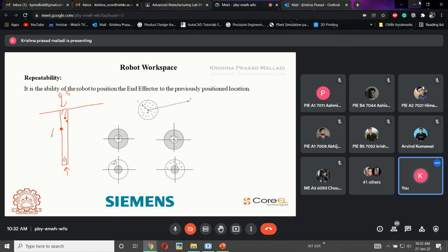This is in no way acceptable. Even though it is maintaining accuracy, even though it is maintaining repeatability at this point itself, it is in no way acceptable. That is why A is the maximum condition with which all robotic engineers will try to perform their operation. They are going to maintain this tolerance, which means the spot welding will be hardly 2 mm or a maximum of 3 mm. The maximum size of the spot weld will be 3 mm.